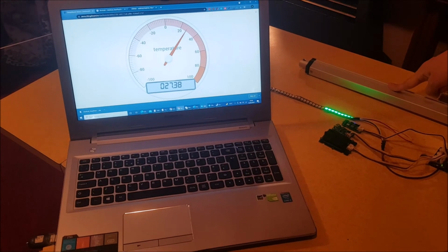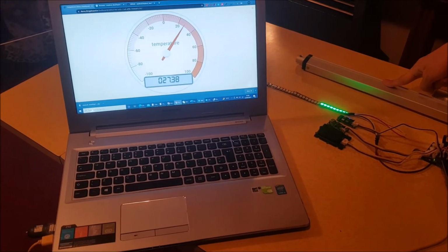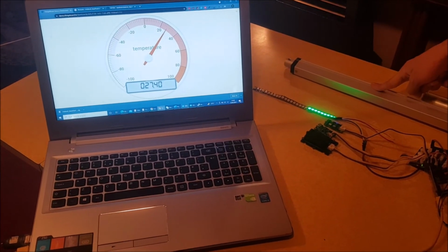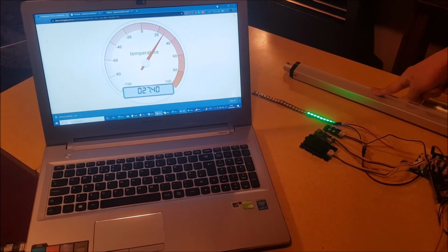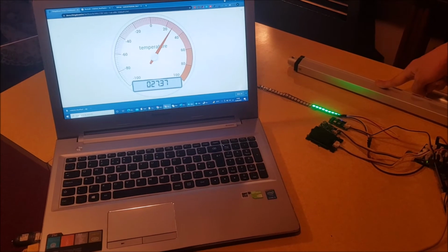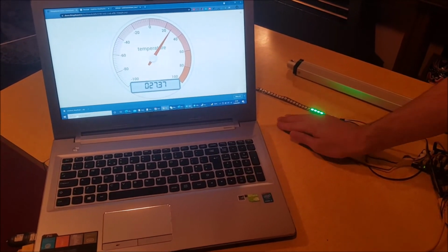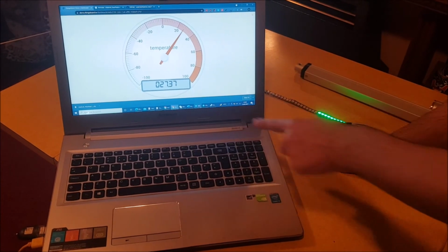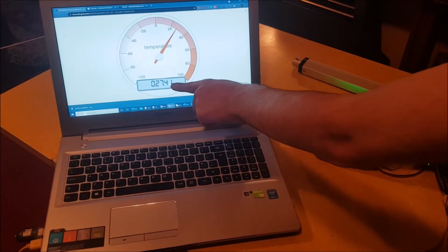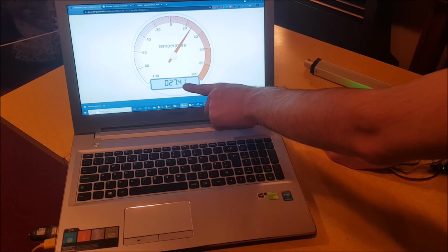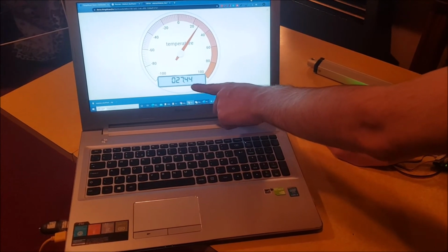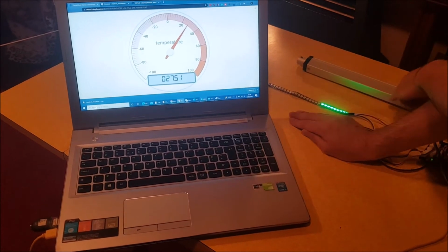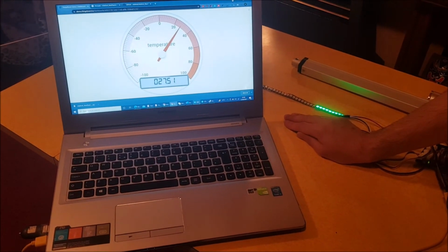The linear actuator is also affected by temperature, not only air quality. So when the temperature reaches a level that is considered uncomfortable, so 28 degrees, the linear actuator should automatically open. We can demonstrate this by covering the sensor. Here you can see that the temperature is 27.37 degrees. When covering the sensor, the numbers are quickly increasing to 27.41, 27.44 degrees, for example. Now when the temperature reaches 28 degrees, the window should automatically open.